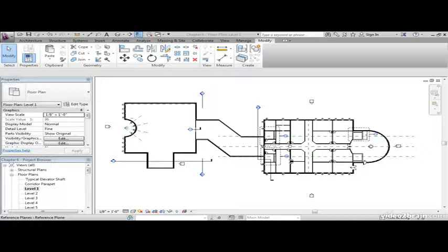In Revit, you can't type over a dimension. This is a good thing, trust me. Once you start dimensioning, you will find that Revit hates to report inaccurate information. As a matter of fact, it's nearly impossible. We can type in a dimension and have an object move into position. That's good, right? The objective of this lesson is to add Align Dimension to our plans.